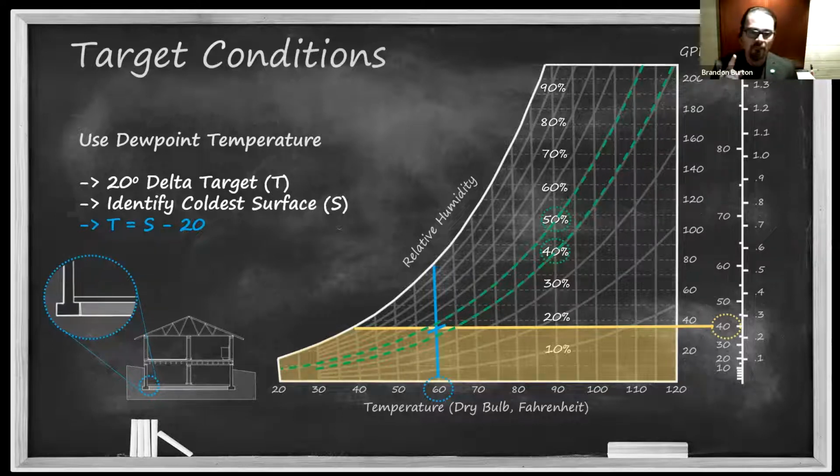But if you listen back to what I just described a couple of times, grab a psychrometric chart and plot that a couple of times, it'll make sense. Not only will it make sense, you'll start to think psychrometrically and accurately about how to set these drying goals within these substructures. So again, the simple formula: P, being target dew point temperature, equals the surface temperature minus 20.